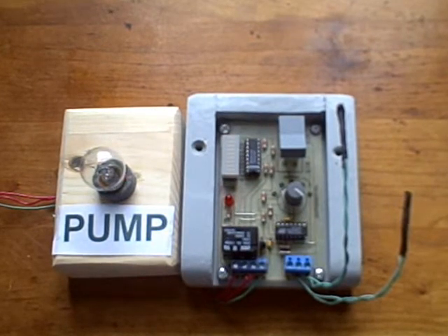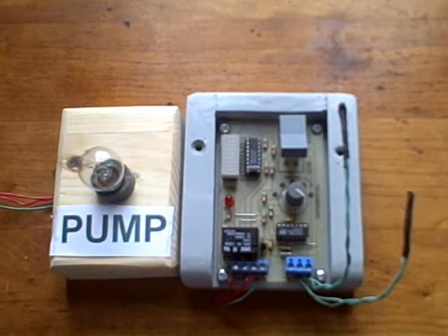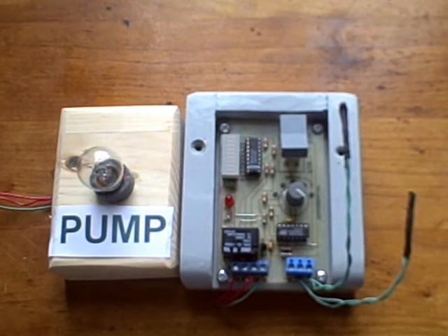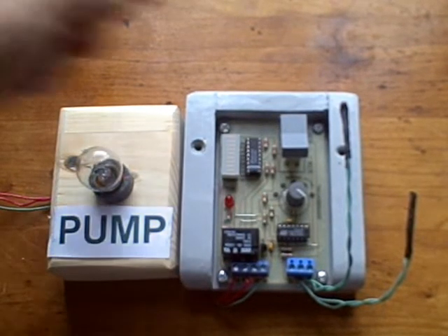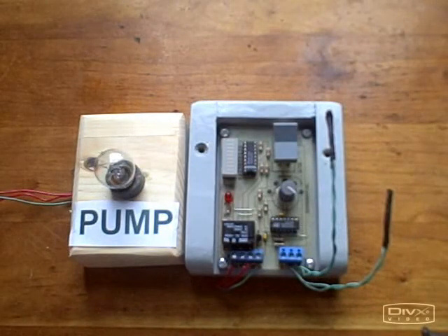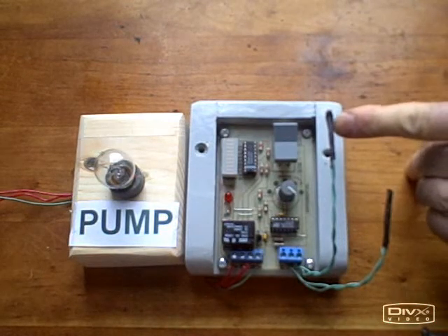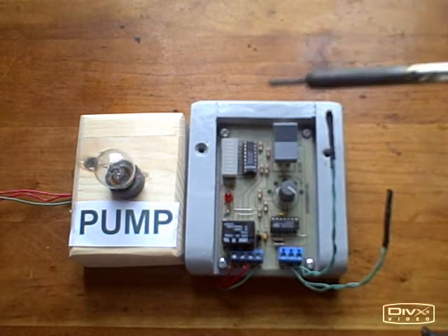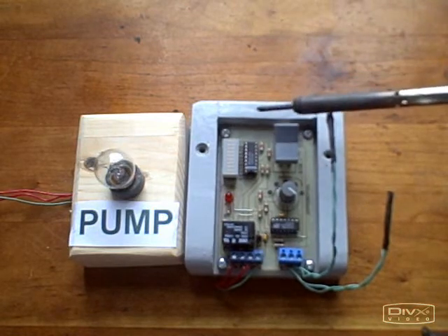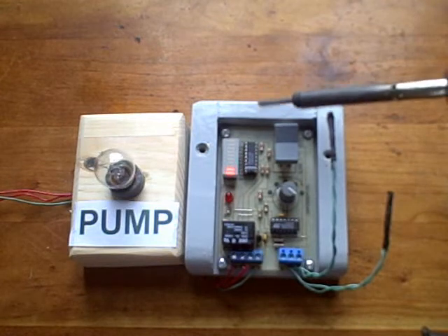In order to turn the pump on, the collector temperature has to be higher than the storage temperature. You know that, right? But first thing I want to do, we'll toggle this switch down. We'll be looking at the storage temperature, and this is the storage probe right here. So I want to heat this storage probe up. Now you can see the temperature start to rise. That's 70.